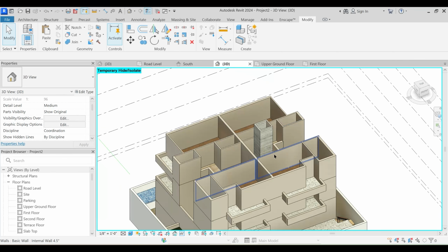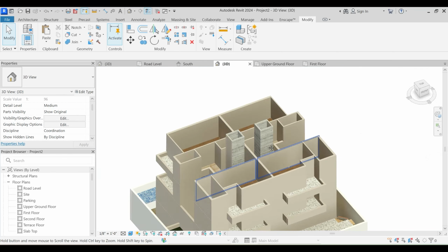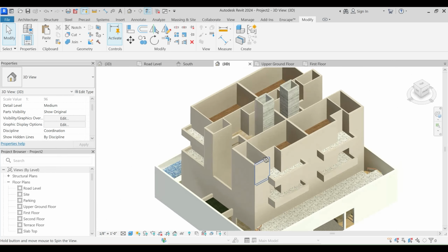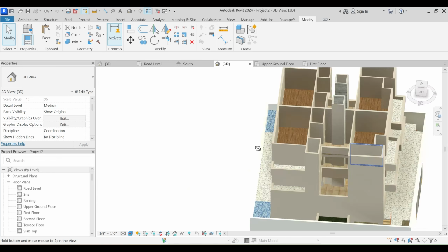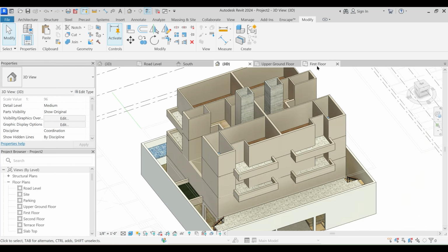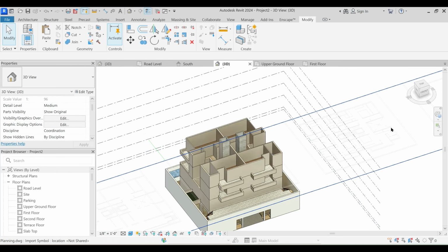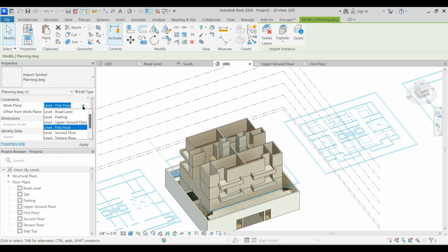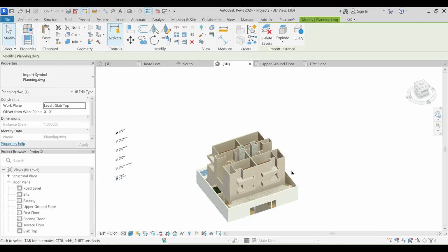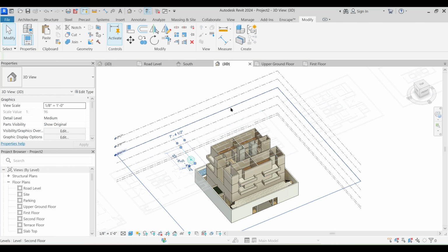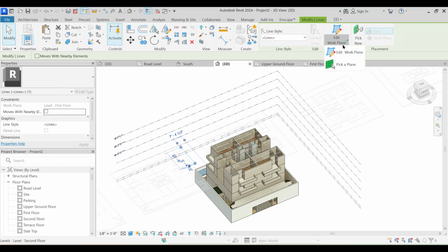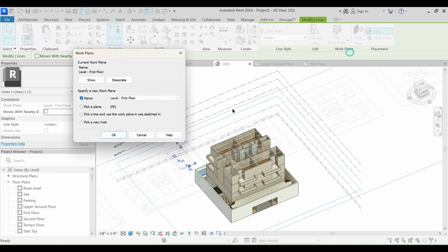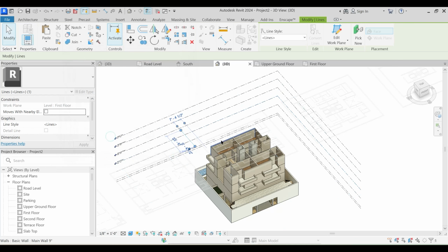Okay. No issues. HR. And finally, now we will create the terrace slab and complete the modeling part. Fine. So what you need to do, just go take this particular floor plan and take this to terrace level, straight away to terrace level. And also this particular reference line, edit work plane, and take it to reference, terrace level. Where is it? Yeah, so this.